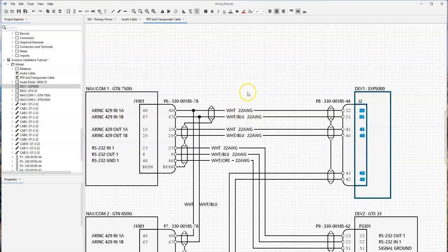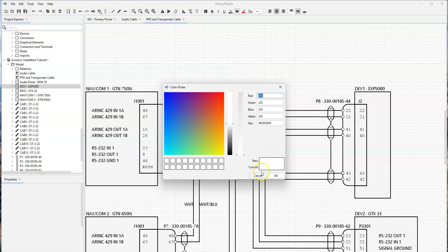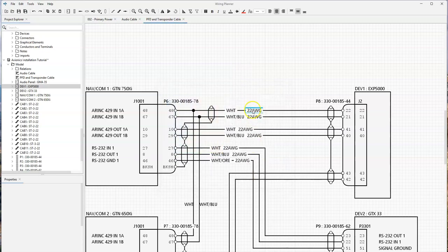We've added the ability to overlay a label onto a conductor as shown here. Some people like to have the label above the conductor, but others prefer to have it on the conductor. And by clicking the Fill tool and adding a white background, you can blank out the wire in the background to make it easier to read.